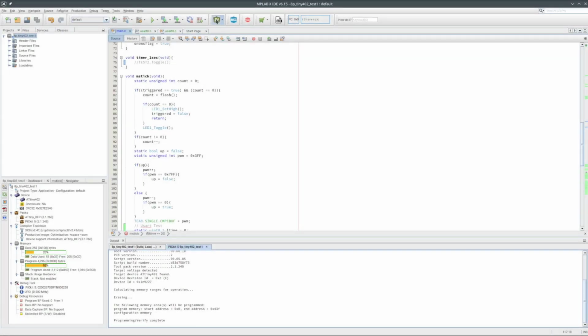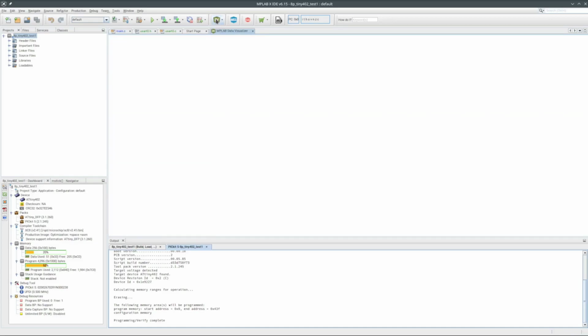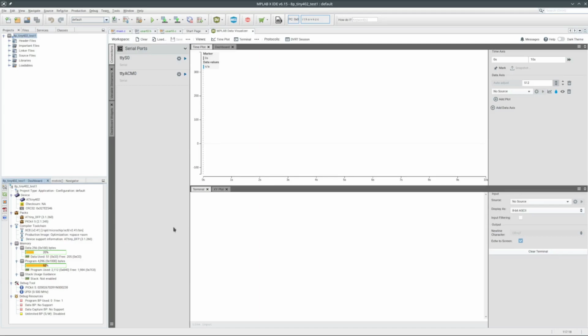One of the plugins I haven't used in MPLAB X is the Data Visualizer. Think I fired it up one time to see if it could see any data port on the ICD4. Of course it didn't. There is the serial port from the Pickit 5 and can set the baud rate to 38,400. Has a terminal section at the bottom of the window. Want the source to be the Pickit 5 serial port.